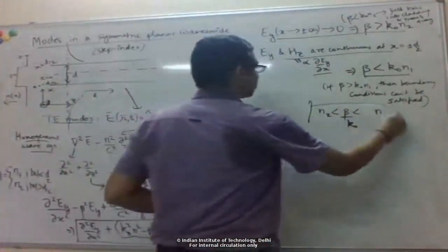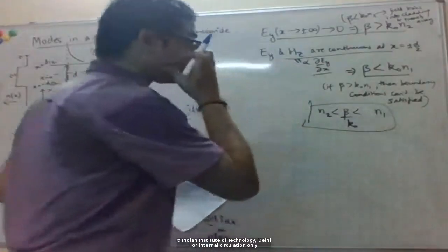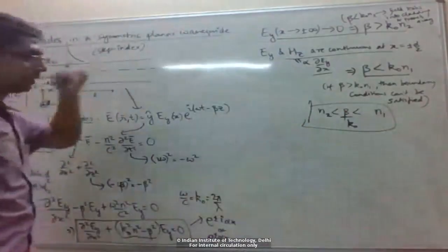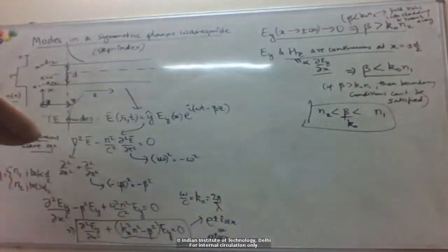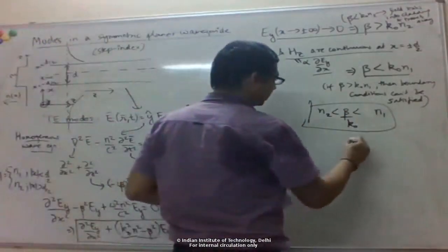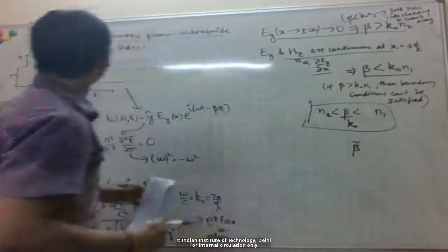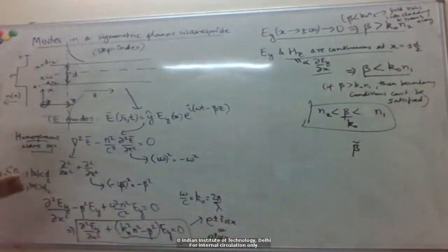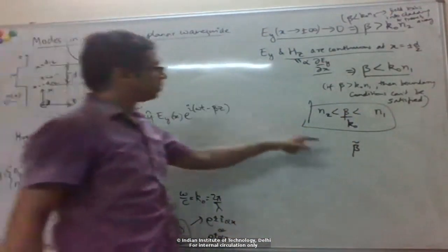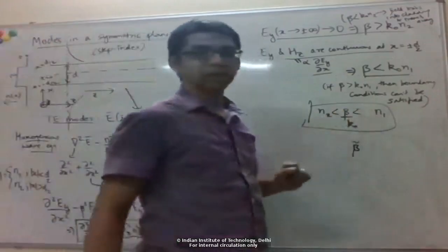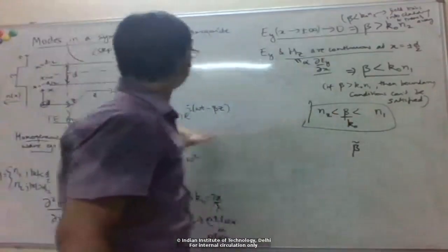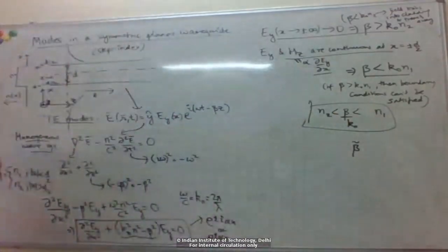Right, so this looks familiar, right? Recall that when we were discussing ray paths in these types of waveguides, we had defined this parameter beta tilde, which depended on the launch angle for the ray. And we saw that the rays would be guided if beta tilde lies between N2 and N1. We saw the same thing, that if it's less than N2, it will leak away.